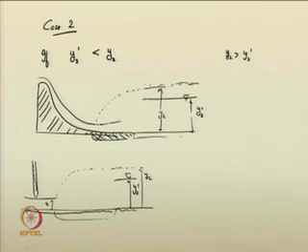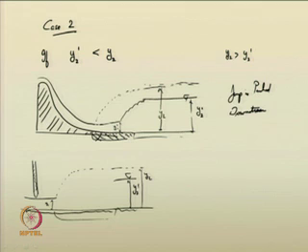We have studied the particular profile and it reaches a depth y1 dash, where the sequent depth of y1 dash is same as y2 dash and the jump occurs like this. Okay. So, the jump is pushed downstream in this case, fine, the jump is pushed downstream.